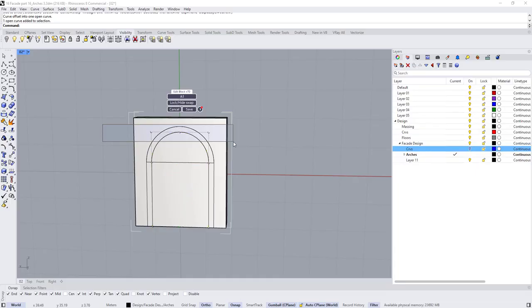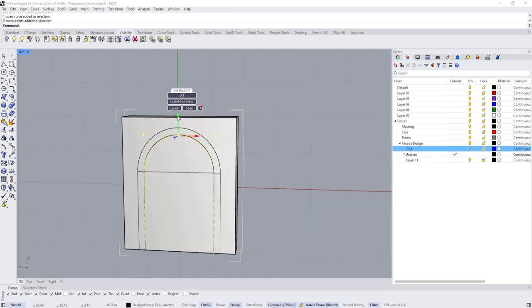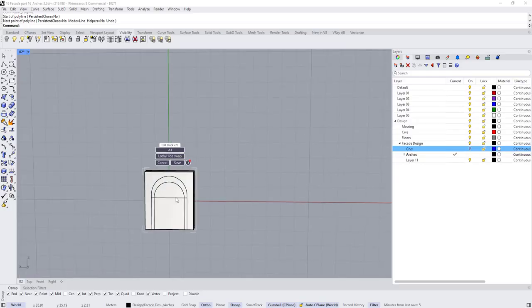And I'm going to select this curve and select these 3 control points and move them down a little bit. I'm still not sure. Maybe instead of doing so, I'm going to select this one and select all of this and move all of this down by a value of 0.2. So the height of the flat part is going to be 2.2 meters, which is reasonable, not bad.